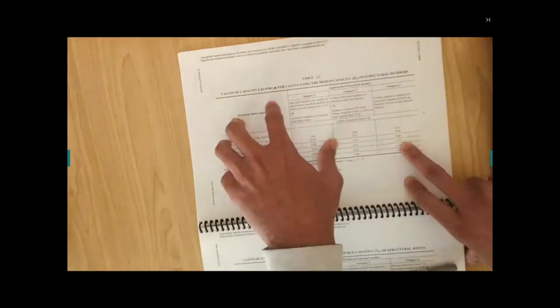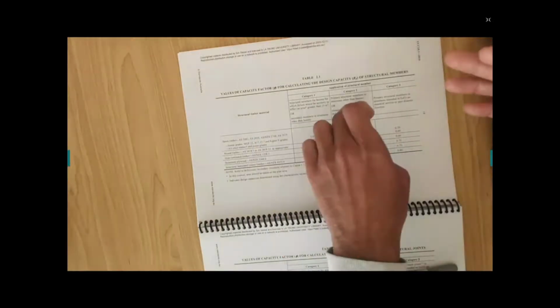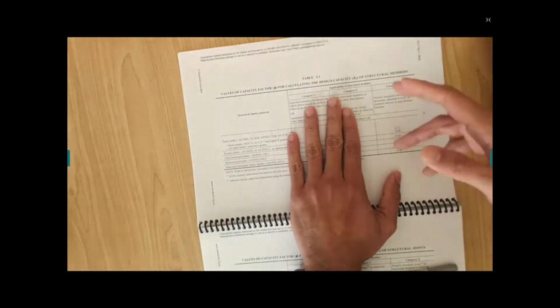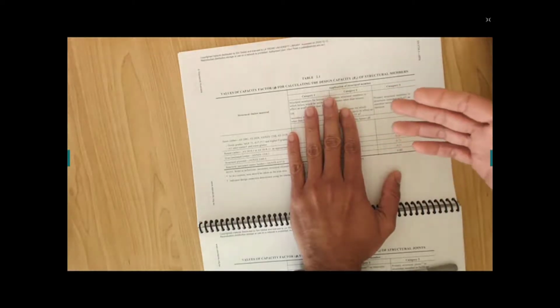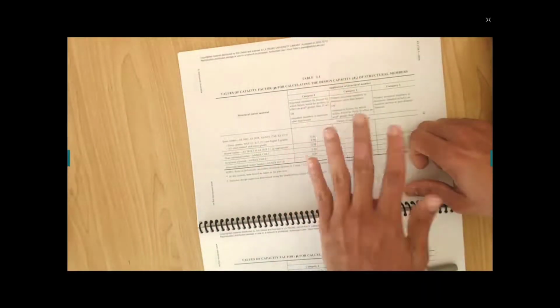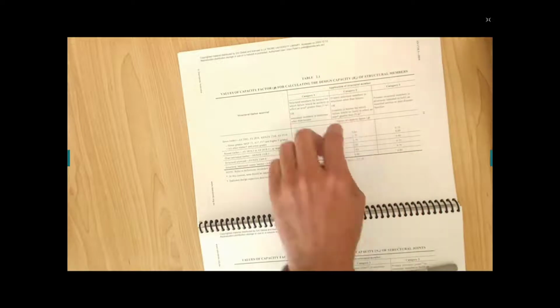So I hope you understand how you're going to calculate these capacity reduction factors. If it is given in the example that this is a primary member of the structure, and if it is broken, then you use this one. If nothing is given, I would suggest going for category number 2, right? Because category number 3 is overkill. If someone says your timber beam is in the hospital, then you go for it. But if nothing is written and it's just an office building or houses or something like that, and they don't specifically mention whether it's 25 square meters or not, I encourage you to use category number 2. This is a more general category, so you are in between. So more generally, we are going for category number 2. Okay, I hope you understand that.